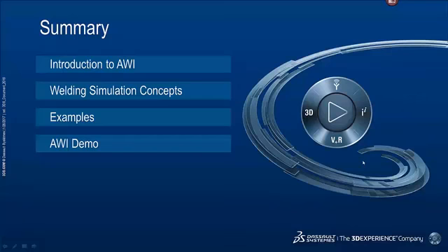Mike, you want to add to that? I was going to say the work being done on the phase transformation will let you look at the heat affected zone. So there'll be output variables that you can look at to see which materials have changed, and there's probably 20 different output variables in that work. But again, that's going to be a few more months before that's available. Yeah, with the phase transformation, of course, you get output variables, a fraction of different phases at a given time snapshot, many different variables you can contour plot.